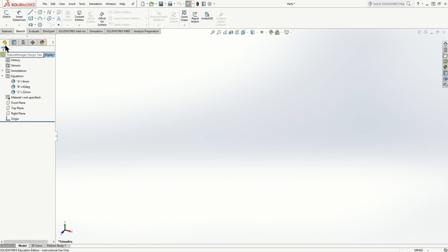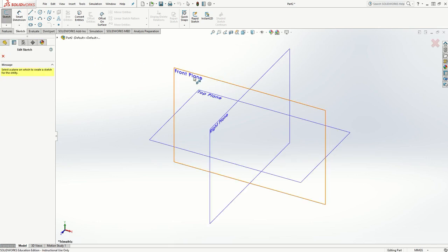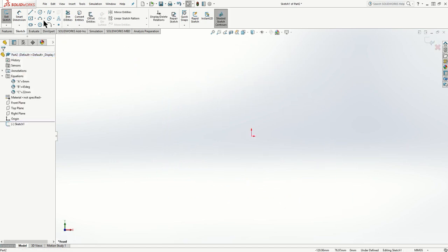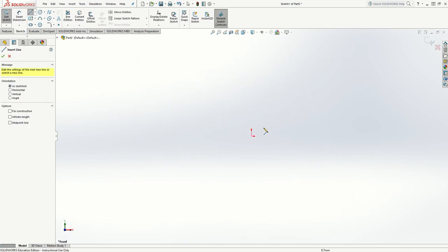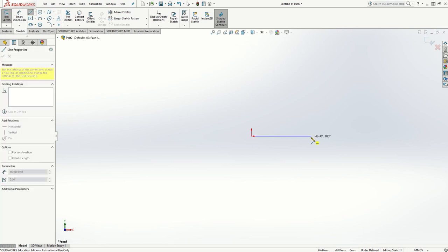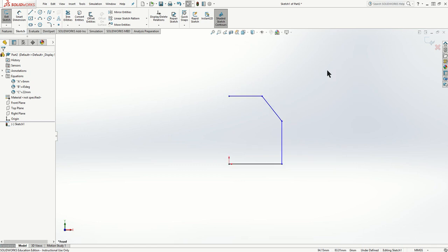Again, to model this drawing, guys, you could do it in many ways. I'm just going to show you this way. Create a sketch, and we're going to draw it in the front plane. We're going to go do the profile. So we're going to draw from here. We're going to go to the right, sorry. Then we're going to go up. We don't care right now about the units. We're going to go back with dimensions. Try not to waste too much time trying to get to dimensions right away, because we're going to use the smart dimensions for that part.